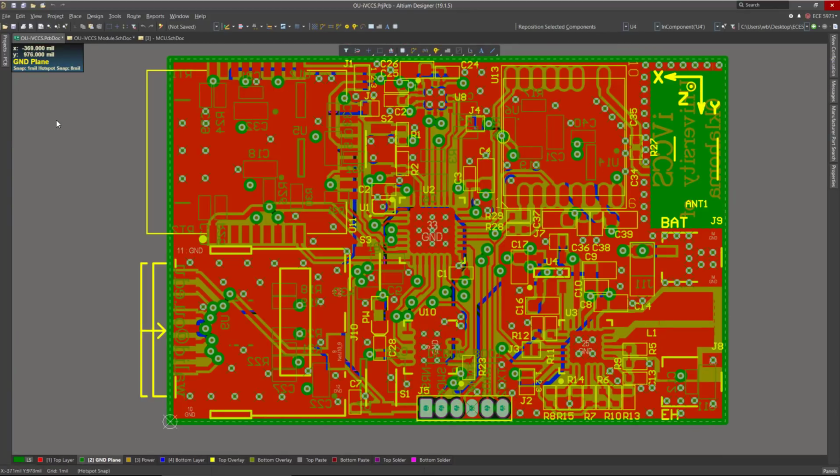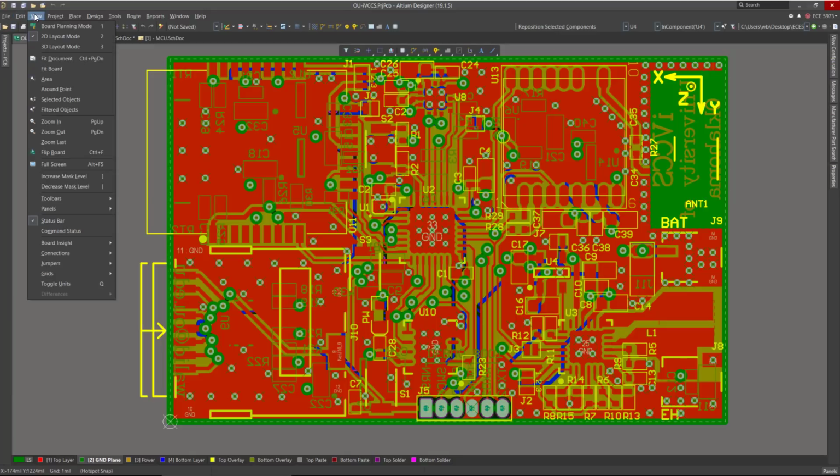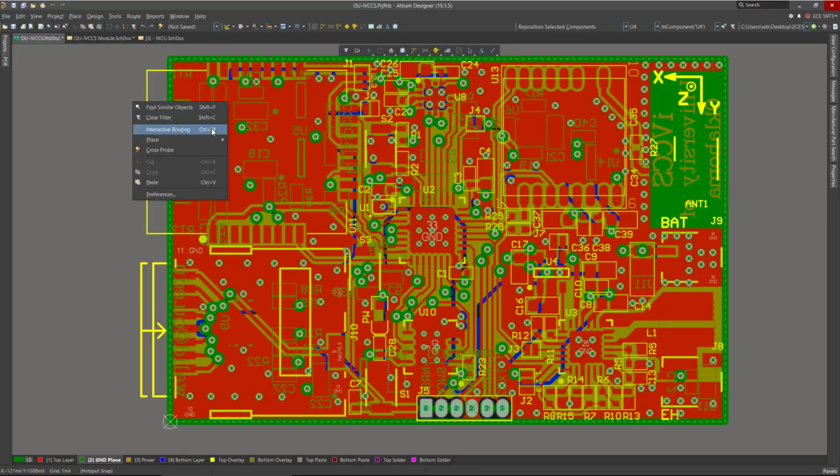Try to explore the right-click menu in the status bar, on the objects, on the free space, and in the schematic and layout. You need to practice to master the tool. Now the shortcuts: sometimes if you don't know a shortcut, you can click, for instance, on the commands and you will see the shortcuts next to the command title in here. Or if you right click, you will also see the shortcut for these commands in the right-click menu.